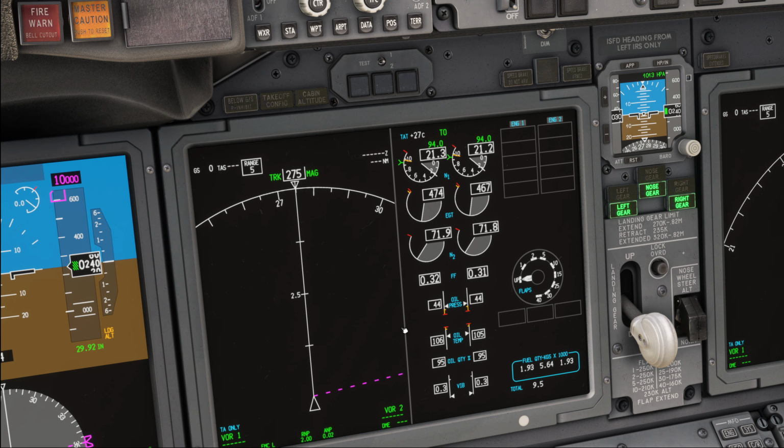Now, the second EEC feature is the thrust control malfunction accommodation logic, which is used to detect an uncontrolled high thrust event on the ground. If the engine thrust levers are reduced to idle on the ground and the engine does not respond to the idle command, the engine will be shut down by the electronic engine control. In other words, when you're landing and you're reducing your thrust levers to idle, if the engines don't run down to idle for whatever reason, the EEC is simply going to shut the respective engine down.